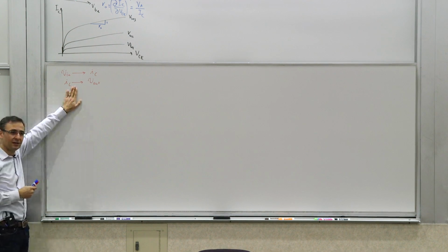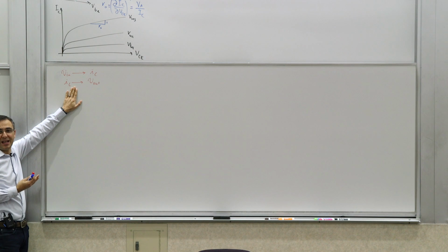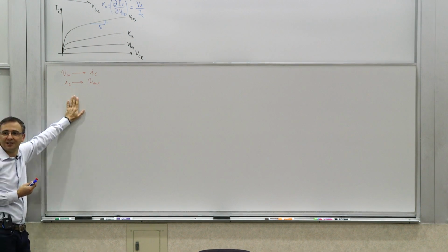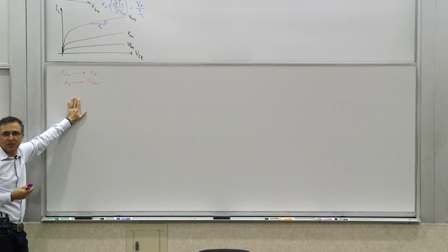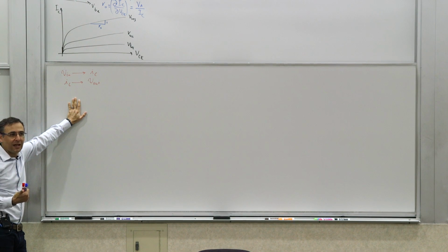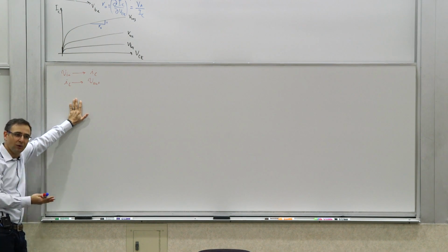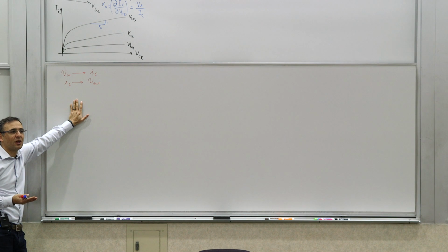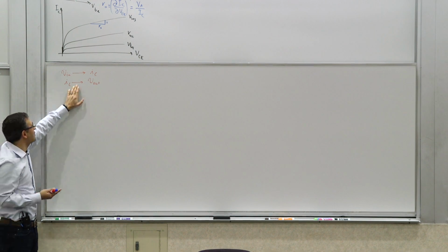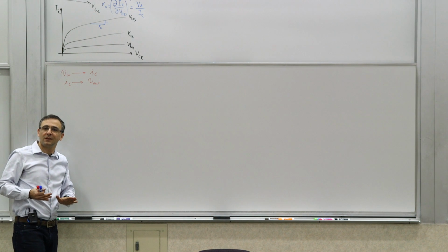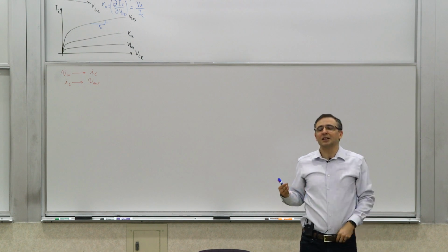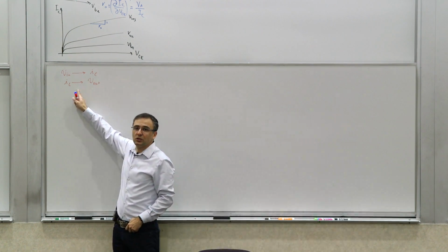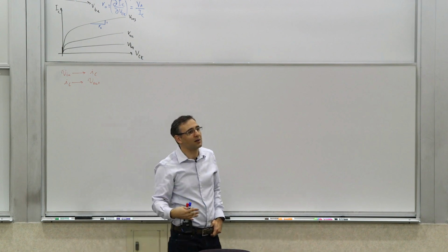What do we need? Well, essentially any two-terminal device does that, at least something that's a general resistor. The general resistor doesn't have to be linear, and it can have any kind of behavior. But you are looking at a general nonlinear resistor that converts this current to a voltage. And then the question is, what kind of resistors do we use? What kind of load do we use? The choice of load leads to a whole bunch of different topologies. A lot of the different topologies that we'll discuss are really a question of what choice of this load we use. And some of that is dictated by the requirements of gain and such.